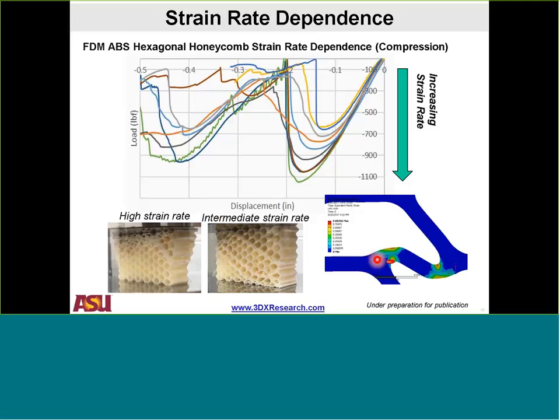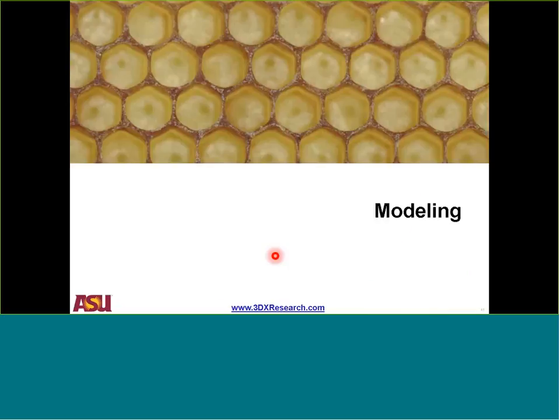So at relatively low strain rates, it is a material response. But when you get to higher and higher strain rates, you start to see a collapse at contact, whereas at low to intermediate strain rates, you start to see multiple locations of failure initiate. So those are my 4 takeaways from the characterization standpoint.